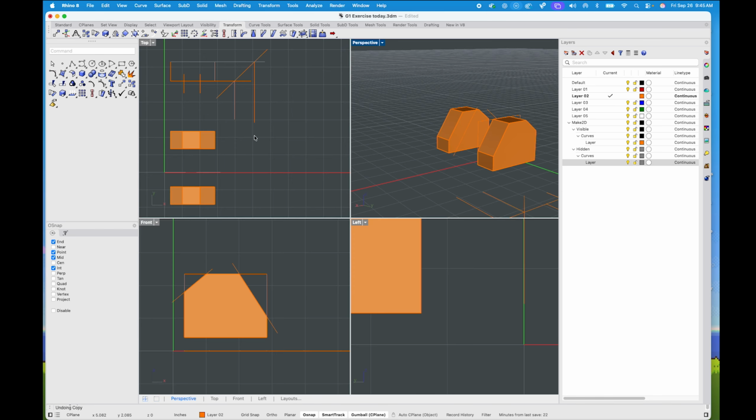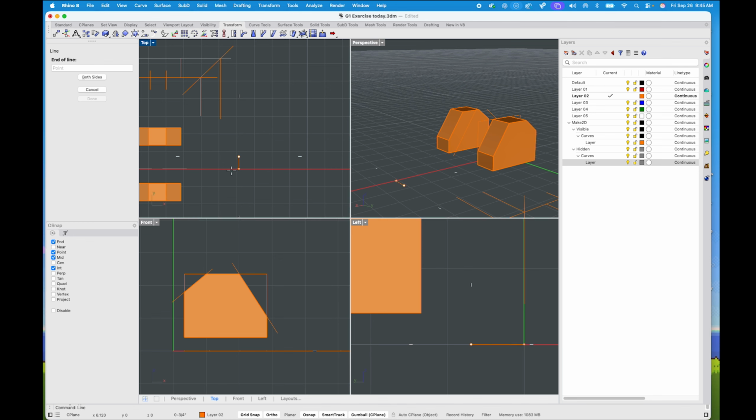However, you'll notice in this ortho mode, if I hold shift, it goes to a perfect 90s, right? If I don't hold shift, it'll stay in that grid view. And I can unclick grid snap while in a command as well. Again, if I hold shift, it'll stay in a straight path. If I don't hold shift, it'll be more free body. If you want to lock in the ortho, you can either do the F8 command there, or down here at the bottom where it says ortho.